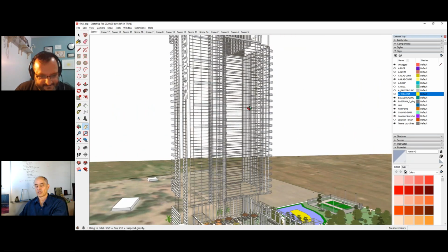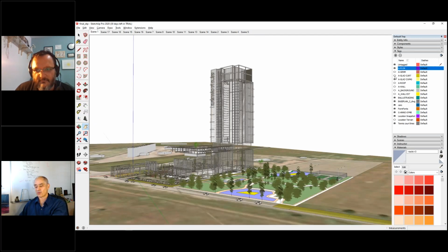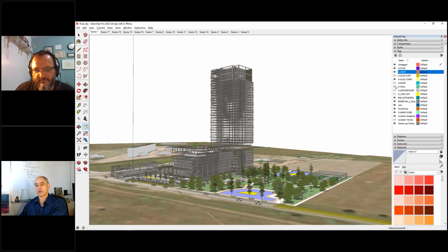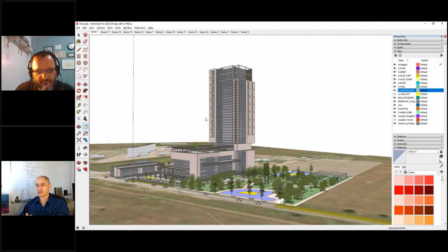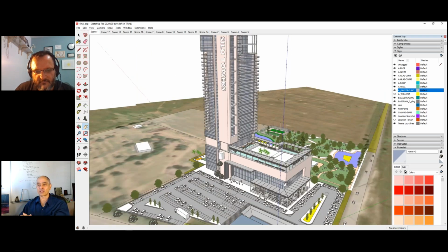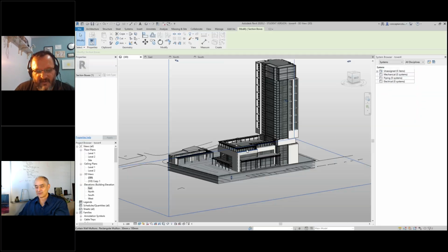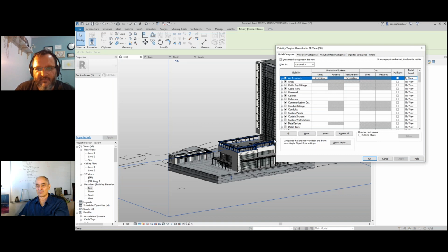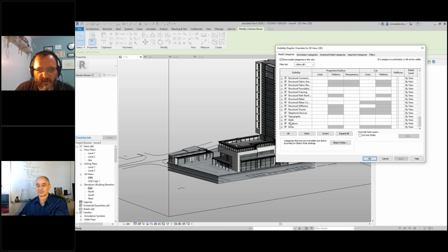Interesting. They resisted layers for forever, and I remember when Revit first came out, one of their claims was, you don't have to worry about managing layers. We sort of show the right thing at the right time, etc. But when you export it, it's creating the equivalent of layers, and in this case, it's called tags in SketchUp. Yeah, Revit does have layers. If you go into the VV menu here, except the way they sort their layers out is, if it's walls, it will be called walls over here, for instance. They're called categories. Windows, they're called categories. They call them exactly model categories.